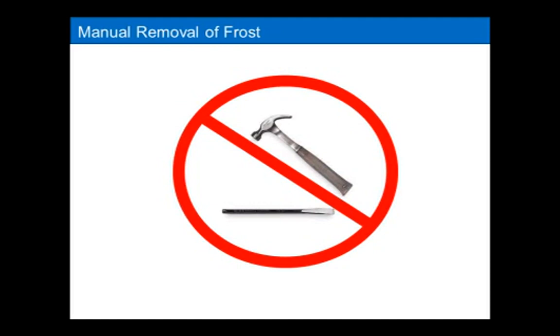So using water is not always a practical means, but there are some coolers and some freezers out there where that is a possibility. So if you can do it, water works great, but a heat gun generally is a pretty safe way of defrosting coils.